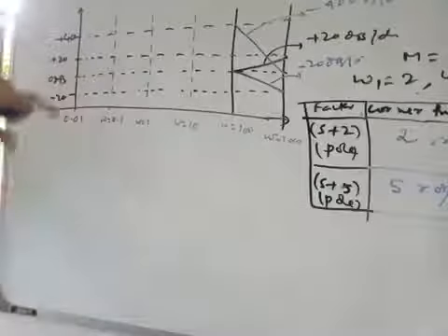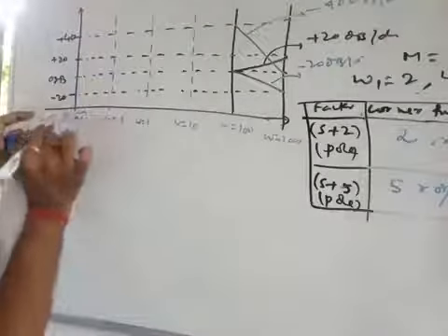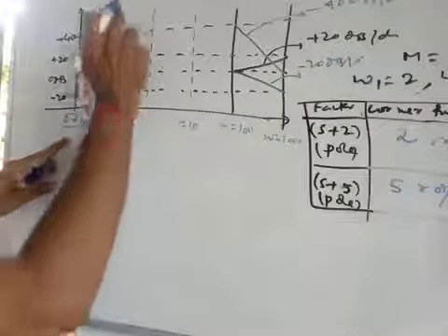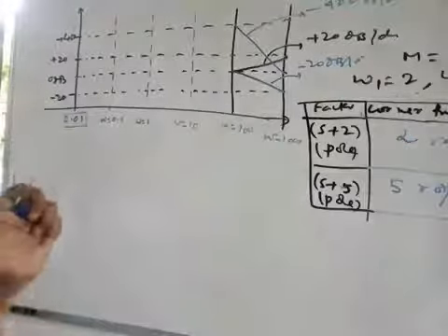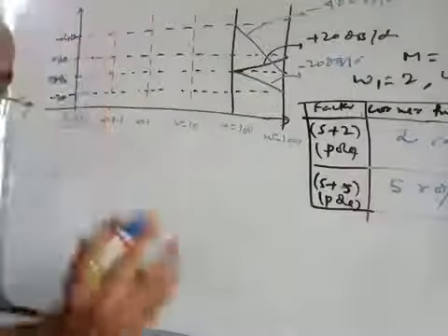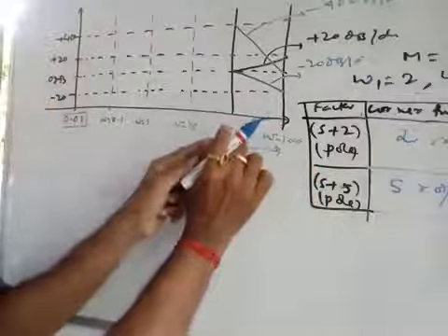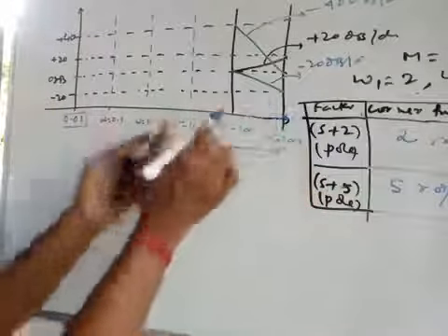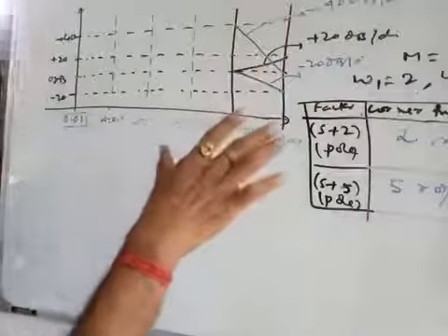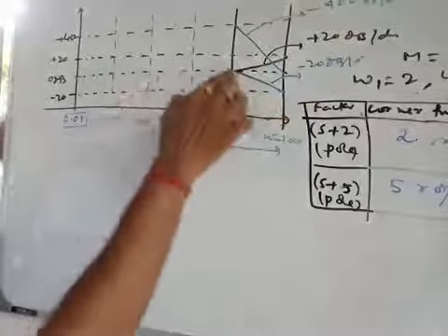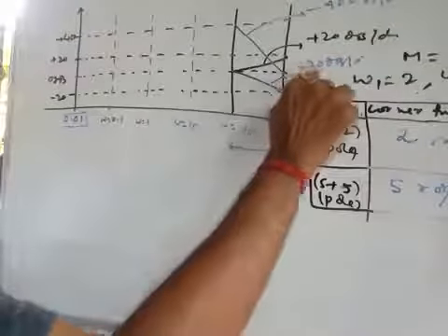So I am drawing a very small part of the graph like this, where you see this is omega equal to 0.01, the initial frequency, and then this graph has 0.1, 1, 10, 100 and 1000. According to our style, how will we draw this Bode plot? We consider the last decade, that means maybe 100 to 1000. This is our last decade, where we have drawn 3 slopes. Maybe 4 or 5 slopes can be drawn here. You see there are 3 slopes I have drawn, going from 0 dB to minus 20 dB. That means this is a downward slope, so this slope is minus 20 dB per decade, right?